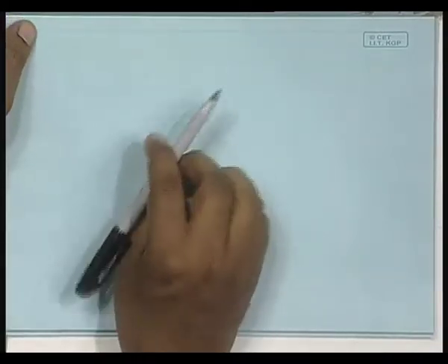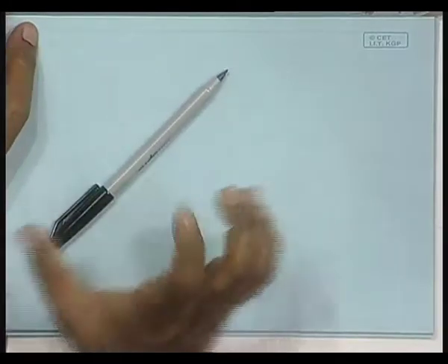Suppose I do not do 0 padding in both, whichever is the shorter one, I add those extra zeros only to that one, so that both the lengths are same, and then do circular convolution. Obviously, I will not get correct linear convolution result, but it is still something better than not doing any 0 padding at all, isn't it? So, what will I get? That is the question.